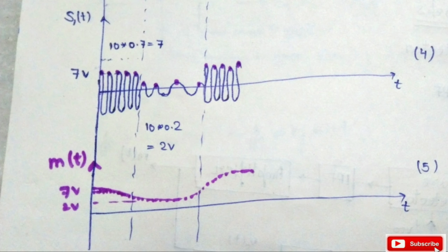But this circuit has a problem, because the gain of the tuned circuit is assumed by us, or it is manufactured by the manufacturing unit, so it will vary, or it is a nonlinear gain. So in the resultant message signal, the amplitude will vary from our basic message signal. In this way we have an error in the message, so that is called a slope error, that is recovered in the balanced slope detector.